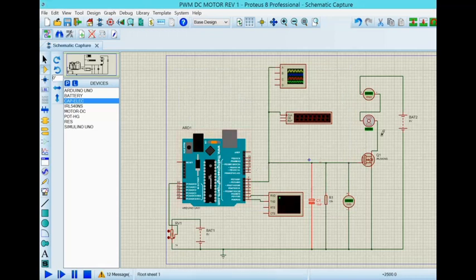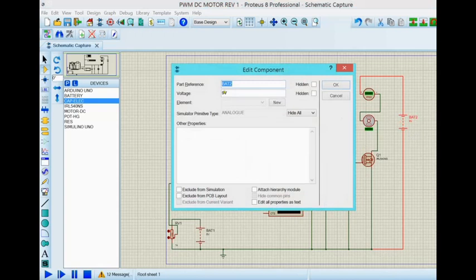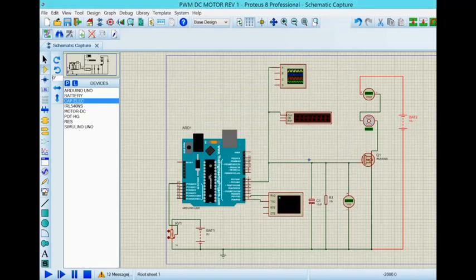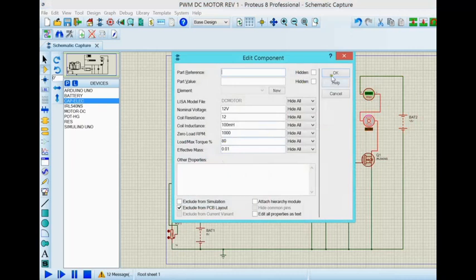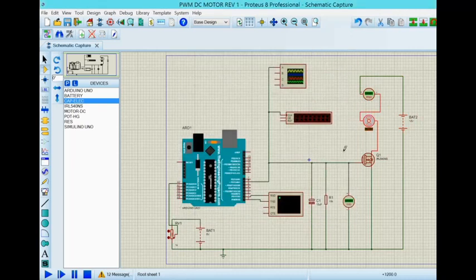Looks like I got everything that I need. The voltage here is not right. Voltage here should be 12 volt, and that will do. I think that I have everything. I can put a diode across the motor, but I'm not at this point. It would not matter at this point for the simulation. So I got the motor, I got the voltage going through, so I can measure the amps going through the motor. I set the motor with the proper amount of loading, 80. You don't want to put that at 100%. Obviously, it would not spin at all, even at maximum current.